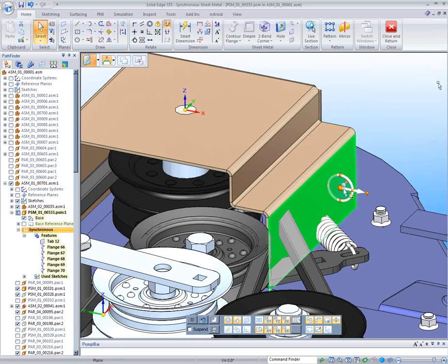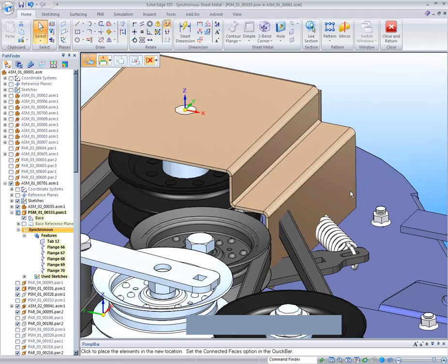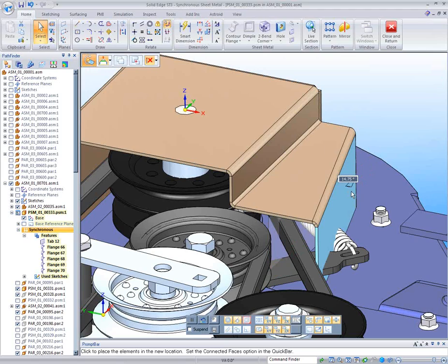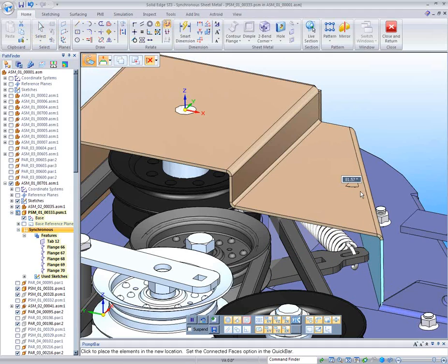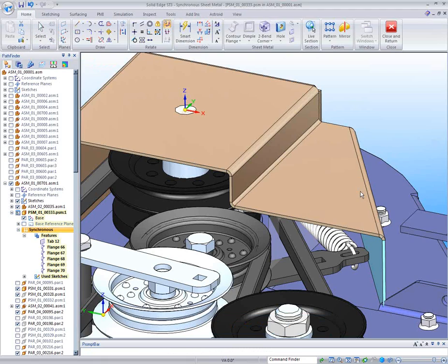So I'm going to take that face and just take my steering wheel. We're going to learn about that in a couple of weeks. And I'm going to take my steering wheel and just flip this right out just until it clears. Now, again, you see me kind of dragging this around. I think I'm going to make that about 32 millimeters. I'll hit tab just so I can see the result.